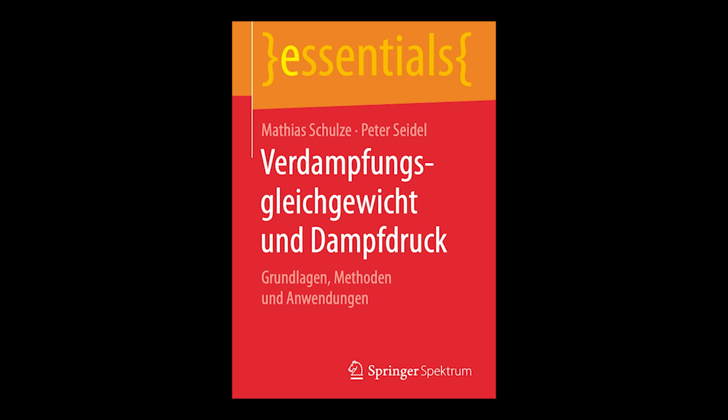And indirect methods? Indirect methods rely on pressure changing some physical or electrical property, which is then calibrated. Examples include the deformation of a tube spring or the change in capacitance or resistance in digital pressure sensors. They offer high precision but need constant calibration. And for temperature, the measurement choice is key to accuracy as well. Of course. We use standard tools like liquid or gas thermometers for simple checks. But for high precision in the lab, we rely on resistance thermometers or thermocouples, which exploit the Seebeck effect. So to determine the actual vapor pressure of a liquid, chemists use two main experimental philosophies, static and dynamic.